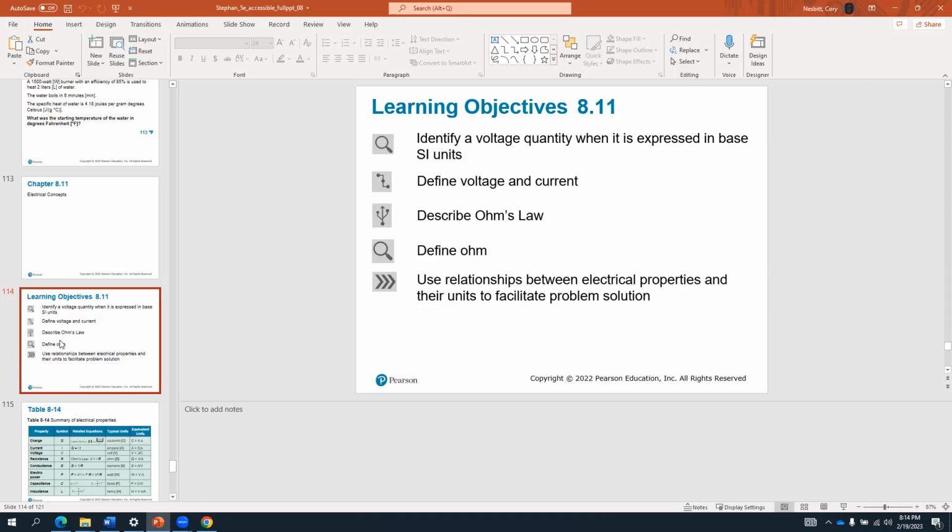And when you think about electrical current, the ampere is defined formally as that constant current, which, if maintained in 2 straight parallel conductors of infinite length of negligible circular cross section, and placed 1 meter apart in a vacuum would produce between those conductors a force equal to 2 times 10 to the minus 7 newtons per meter of length.